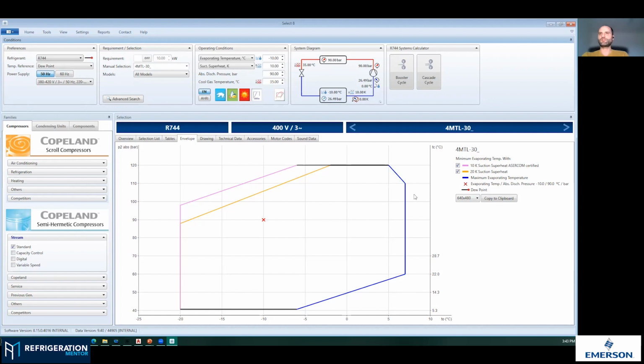Just probably one thing, one kind of warning is that if you operate the compressor with variable speed, you need to set up also this maximum current protection in the drive. Yes. So then whatever system you have on the compressor, you need to set up properly the maximum current protection in your drive.